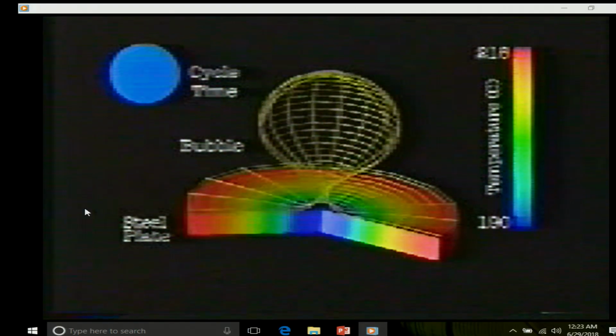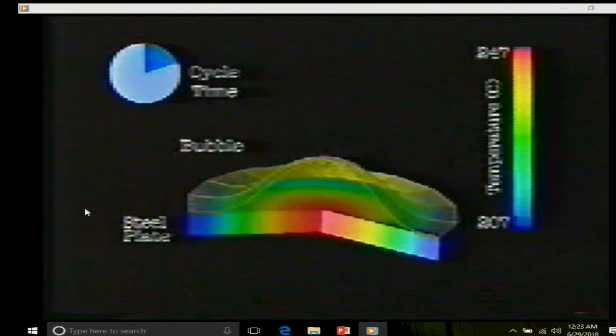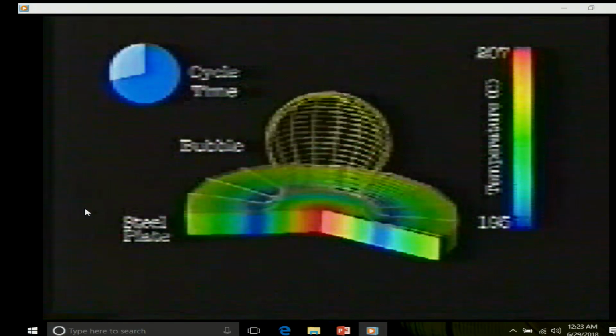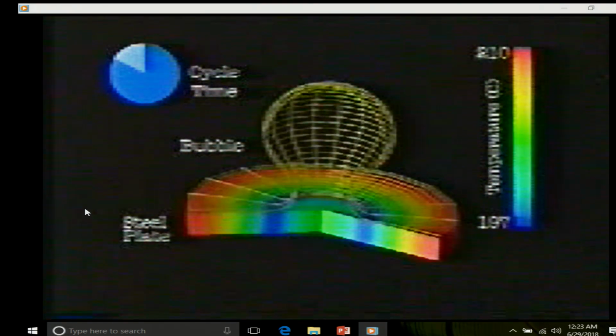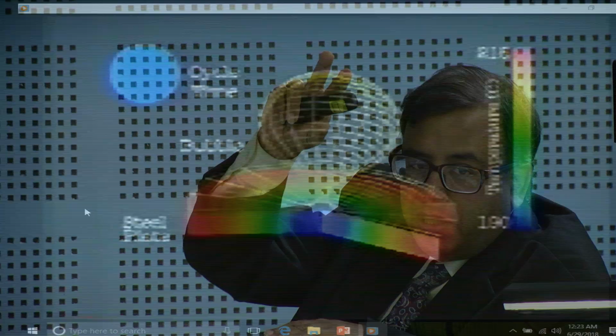Now, since the 1960s, people had theorized that there is a cold spot, but nobody could model it to begin with, because people would assume a certain static shape for a bubble and do the analysis, and number two, nobody could measure it. At least now I have a model that predicts it, starting from a simple Rayleigh-Taylor instability. We start with a simple configuration of a vapor layer with a liquid layer on top, and let the computer program figure out the Taylor instability and those oscillations of the vapor bubble.